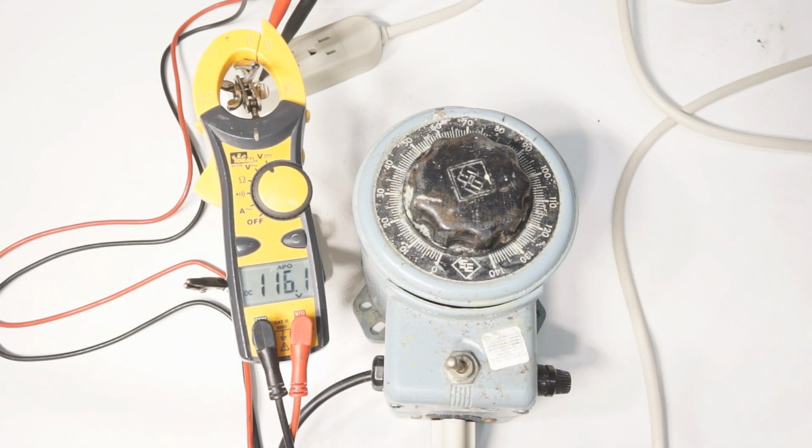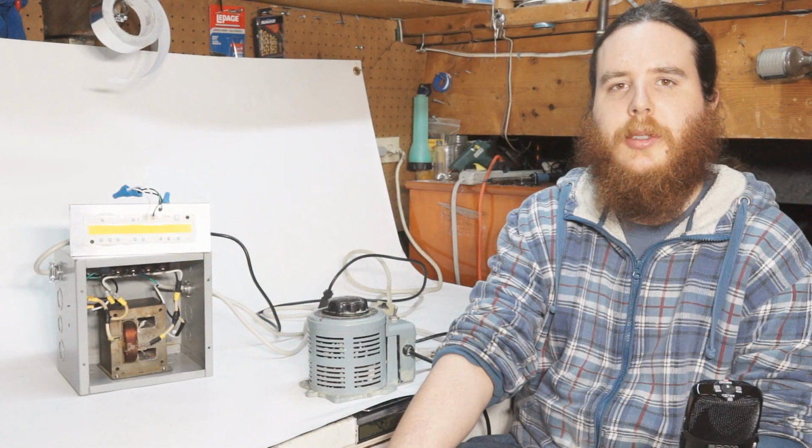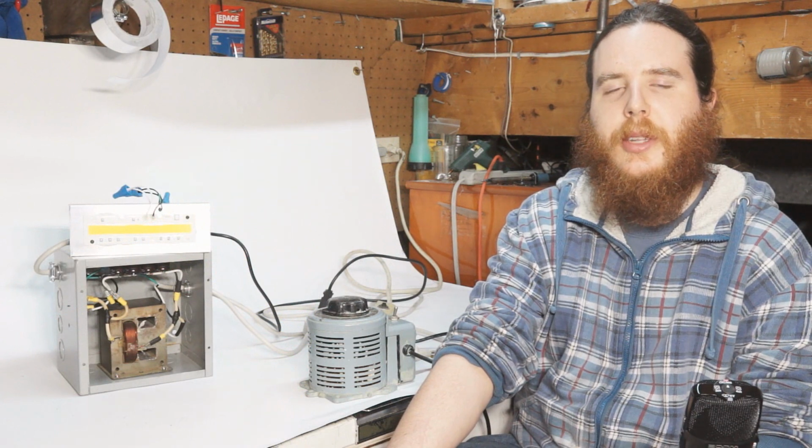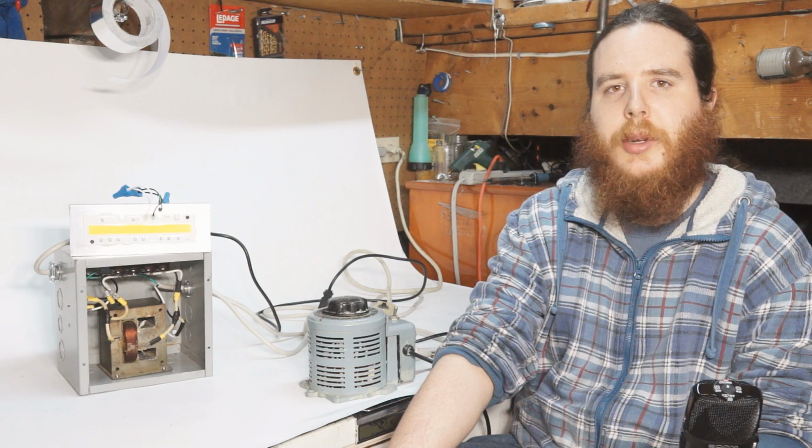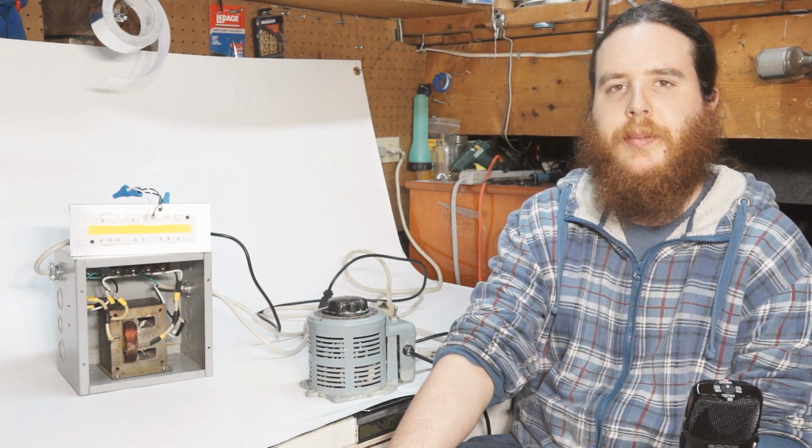charge even after the power supply has been turned off. To mitigate this problem, I've put high-value resistors across all of the capacitors in order to dissipate the charge once power has been removed. Although this isn't a permanent solution, it is significantly cheaper than any of the commercially available high-speed video LEDs, and it allowed me to learn a little bit about analog power supplies and filters.